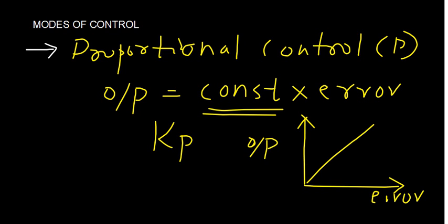Whenever we speak about a mechanical or electrical system, because of the inherent inertia, whenever you want to take out the output which is just proportional to the error and some constant, it is always bound to have some kind of oscillations. So therefore in sophisticated system design, generally proportional control is not preferred,